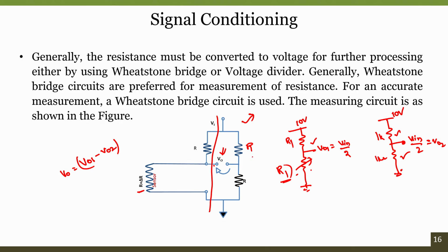Right. So, this is the advantage of going with the resistive Wheatstone split circuit. Another advantage is, when we have two different sensors, one with R plus delta R and the other with R minus delta R configuration, or with the same R plus delta R. Suppose this is another sensor which is R plus delta R T, but it is only for measuring the temperature, whereas this is R plus delta R, which is based on the changes with respect to the physical measurement, and this one is for the temperature compensation.